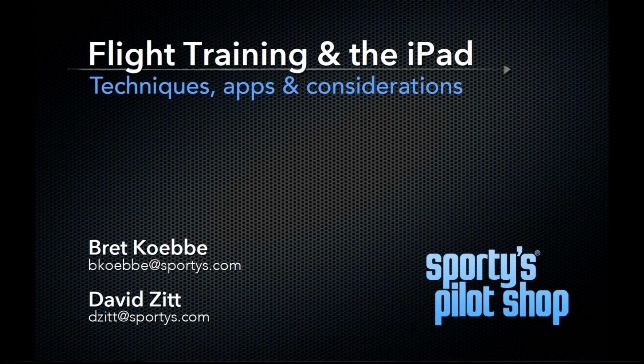Go above and beyond whatever the application does for security and its own backup, and store a copy yourself on some kind of interval basis. As far as legalities, yes, you're fine doing a digital logbook. Again, I mentioned there are ways to do electronic signatures in the applications. If you wanted to, for your endorsements or particular instructor signatures, you could also have them sign a paper reference book, if you want to have that in the purest essence of their signature, if you're really concerned about it. But yes, it's perfectly legal to do electronic logbooks and store all your data, as long as, more importantly, you are meeting the accuracy and minimum time requirements for your certificate or whatever rating you're going for.